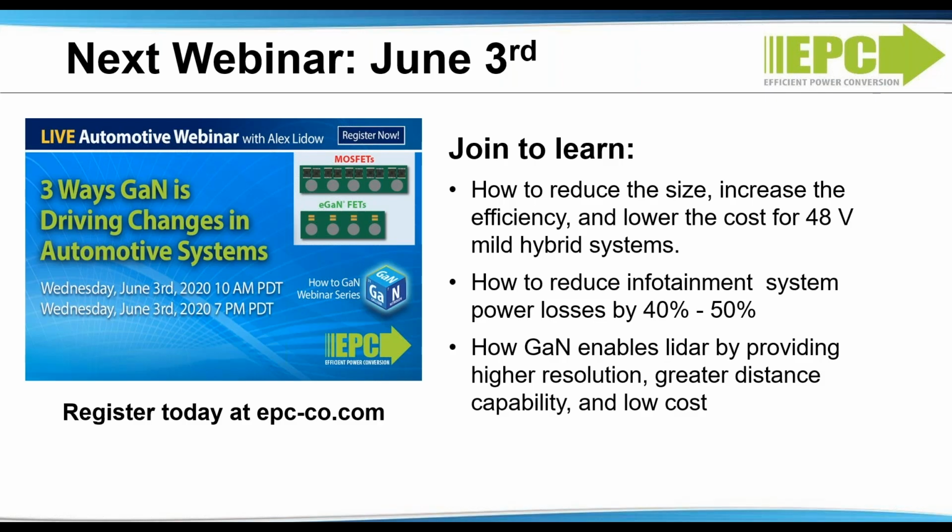A typical package, even your best MOSFET package, will have about a nanohenry inductance in between the drain and the source. So that's added to your power loop. What that does is it causes overshoot in your power loop, in your switch node. And the energy in that ringing and overshoot is the primary source of EMI and EMC.